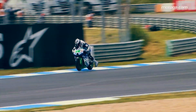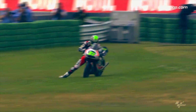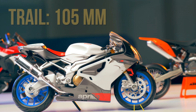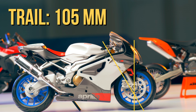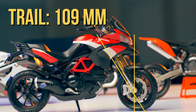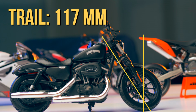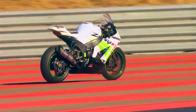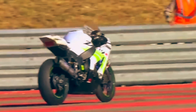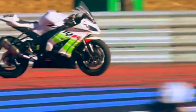So why is trail so important? Well, trail is what makes it possible to stay balanced on two wheels, because it forces the front end to stay straight when a motorcycle is driven forward. So the further the wheel is behind the steering axis, the more stable the bike is, and vice versa. So less trail equals quicker steering bike, but also more unstable bike. The effect is obvious if you have seen a motorcycle going down the track in a straight line when the riders fell off. The bike wants to go in a straight line because of trail.